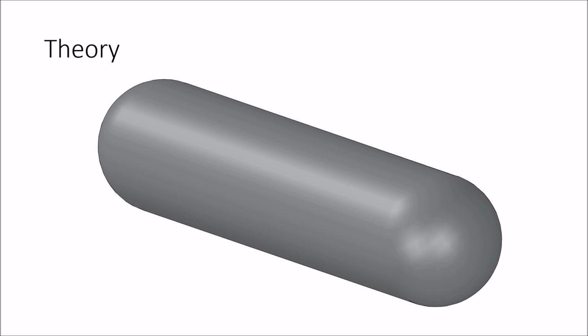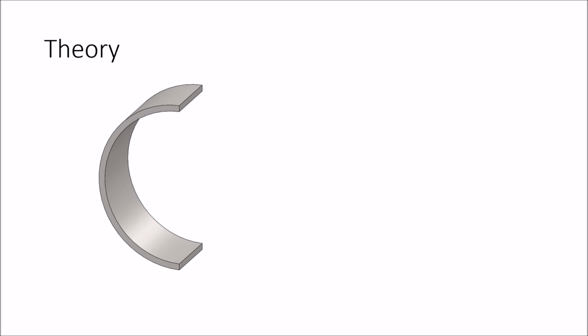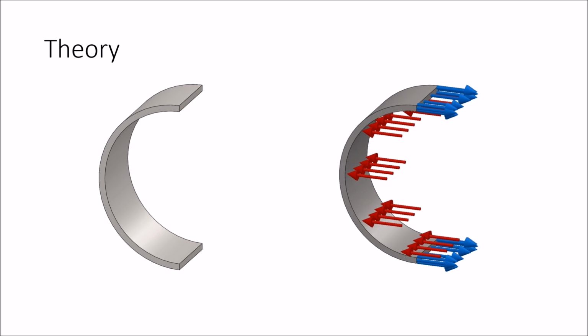First, when we look at a longitudinal pressure vessel, we notice there are two different geometries. One is the geometry of the end cap, which is spherical, and the other is the geometry of the side walls. First, we'll look at the side walls. We can make a cut that is very small. Now let's imagine if that cut had pressure applied to it. As you notice, the amount of material that is resisting the pressure is quite small. Due to this, the stress that will be developed in this manner will be much larger. That is why the equation for this portion of the pressure vessel is PR over T, and not over 2T.